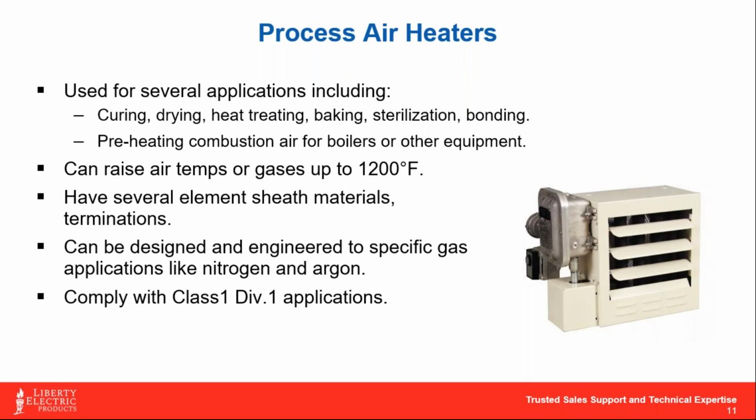And again, it's a product that can be engineered specifically to a particular output, size, and voltage requirements. And these heaters are, again, powerful. They can get up to 1200 F. Essentially inside of this heater, you really just have the guts of tubular heaters. So again, the same laws of physics apply as with those component heaters we just looked at.